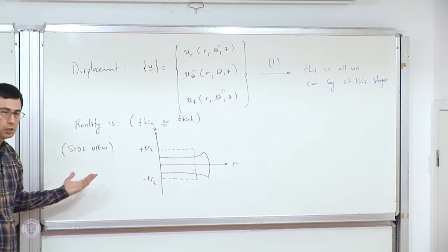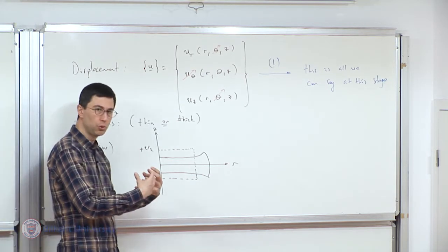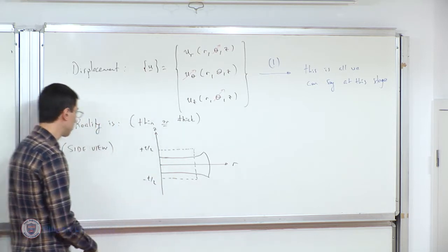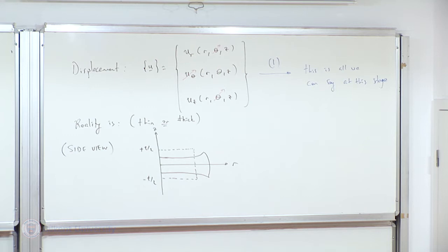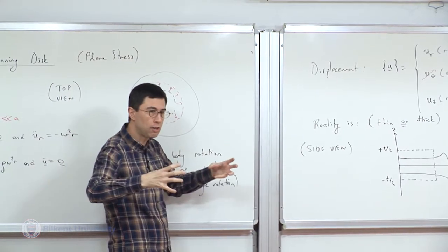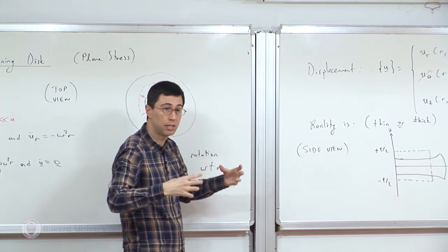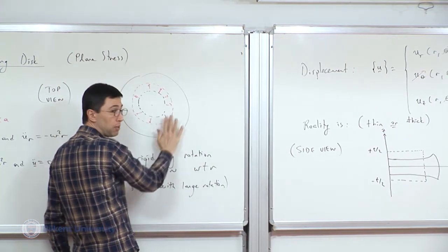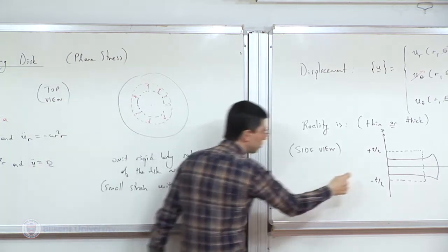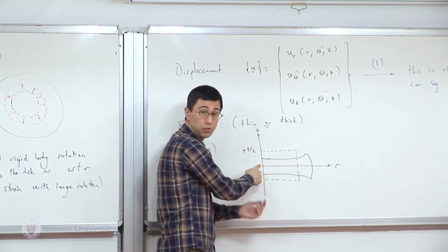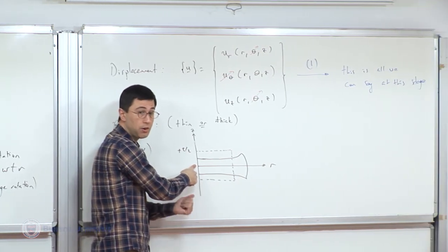By way of analogy, right? So there are forces due to rotation. This is the center of the disk. It's the middle. Right? That's right in the middle. So if there is more material surrounding a point, those points will try to move and exert more, let's say, radial stress on this point, for instance. There's so much material surrounding it. So the stress, it turns out, at r equals 0, the radial stress, it turns out also the tangential stress, and we will eventually find these out, they are the highest.